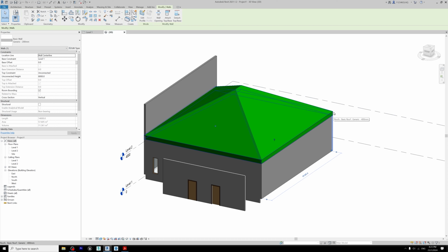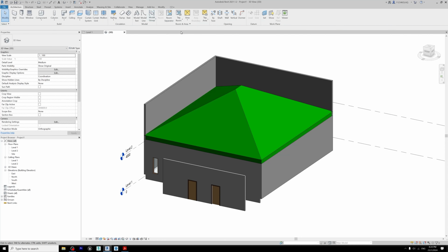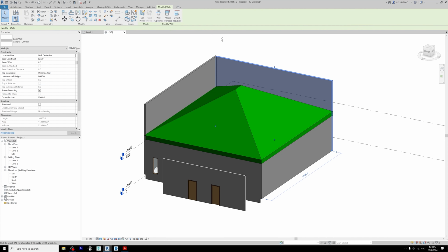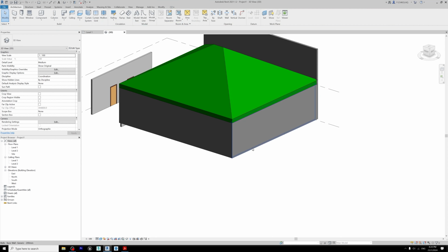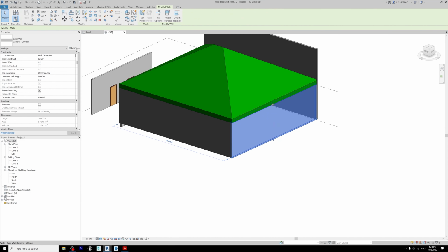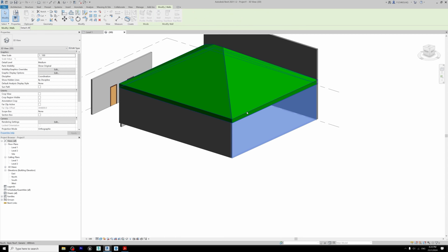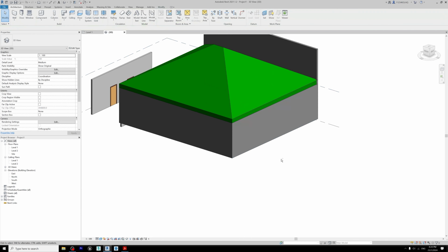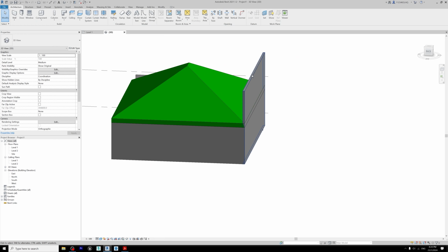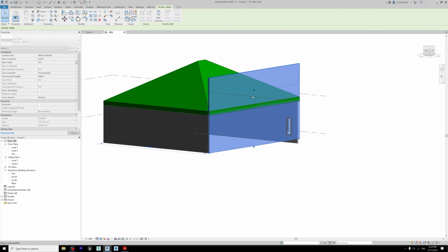Let's say there's something that moved or you want to move something, it's going to tell you that it's attached. So I prefer not to use attach top/base. This is what it does. If you have attached it previously, like we did just now, I'm going to redo it. Now I have it attached. You can see now that arrow is gone. Let me detach it to show you. Detach. Now you can see this wall has that arrow. You have more control over it. So that's why I don't like to attach these walls to the roofs.